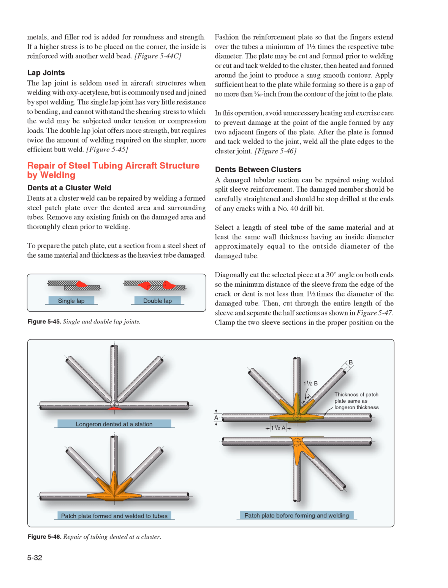In this operation, avoid unnecessary heating and exercise care to prevent damage at the point of the angle formed by any two adjacent fingers of the plate. After the plate is formed and tack welded to the joint, weld all the plate edges to the cluster joint.